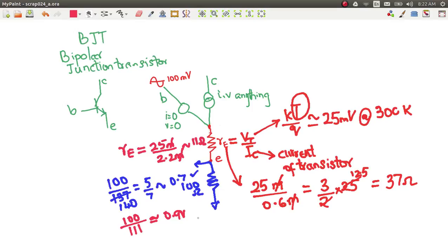So now if you look at the output, is a resistor. Now for AC purposes, as I have mentioned, the supply doesn't change, so we are only interested in things that change. So as far as we are concerned, this is sort of at ground, and whatever current we are pulling here because of this voltage, the nullator will pull out the same current from the resistor, and if this voltage essentially doesn't move, then the change is negative. So if I apply a positive voltage here, the excursion here would be negative first and then positive.